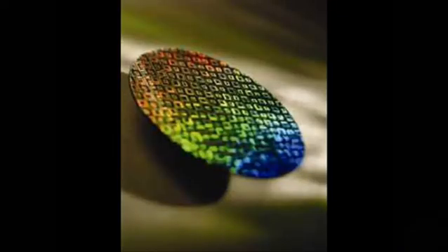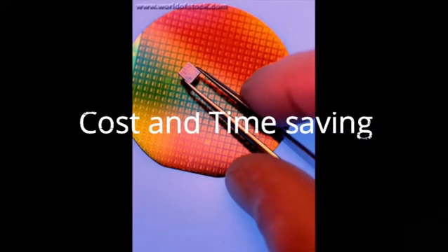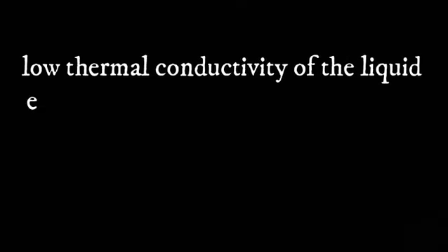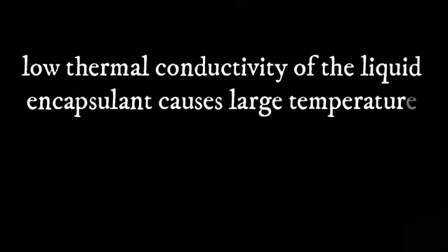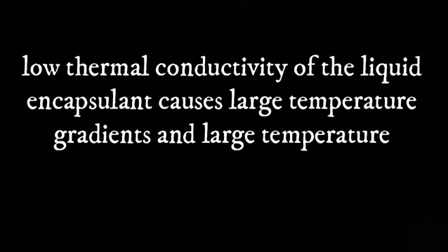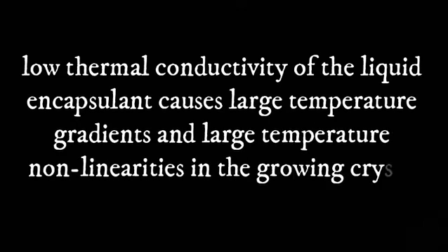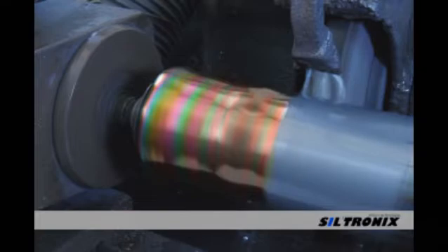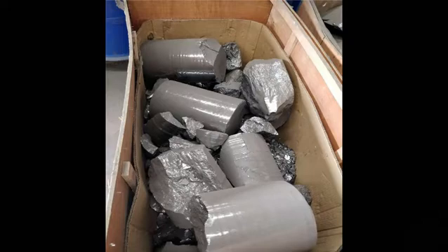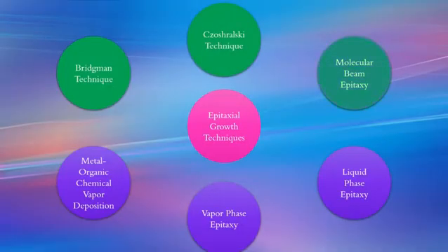The advantage of this method is cost saving by multiple use of the crucible and saving the time for cooling down and heating up periods. However, the low thermal conductivity of the liquid encapsulant causes large temperature gradients and large temperature non-linearities in the growing crystal. This is unfavorable with respect to the crystal quality, as a relatively large number of structural defects are generated in the crystal. On to the next one, molecular beam epitaxy.